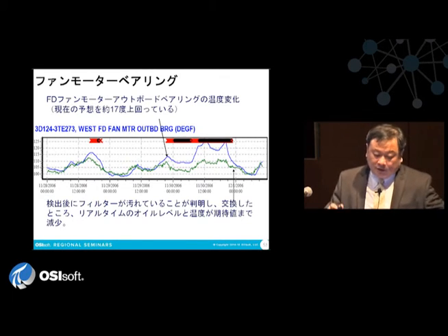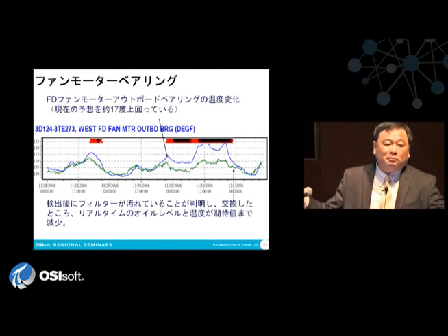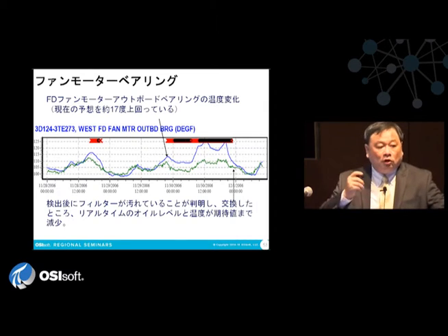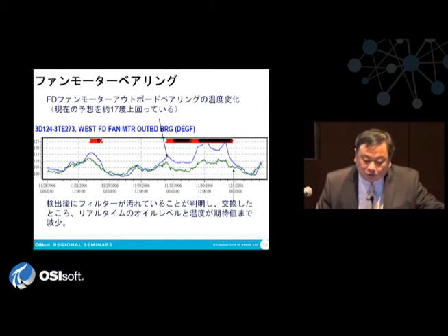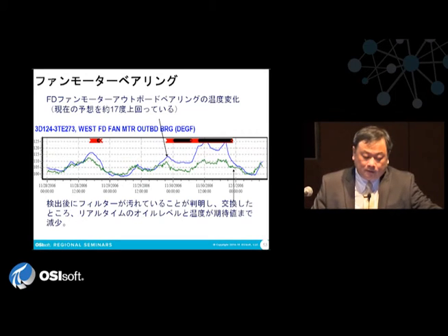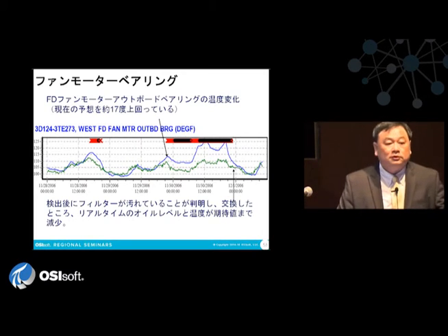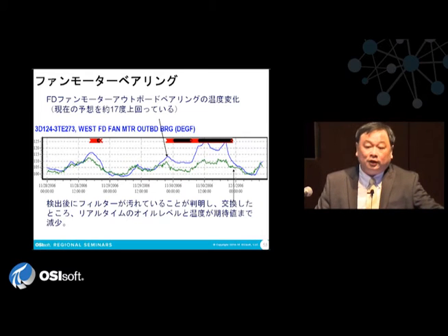So if they exceed some sort of range, it will put a red cross here. And once you accumulate a certain number of crosses, it will automatically notify you there is a problem, for you to do a check. So after we checked, we found the oil filter was too dirty and needed to be cleaned.